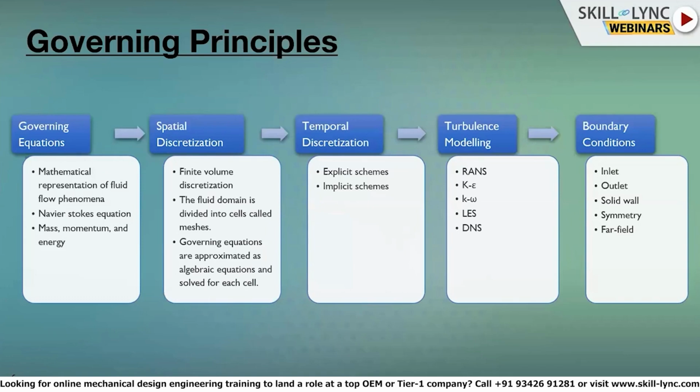That is called explicit time marching. Whereas in implicit schemes, you would not know the previous time step values and current time step values, and you end up with a set of equations in the form of Ax = b. It's a system of linear equations, and you solve all these equations simultaneously using certain numerical schemes. Those are called implicit schemes.